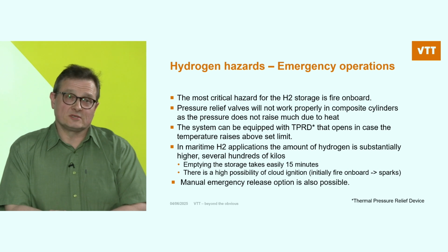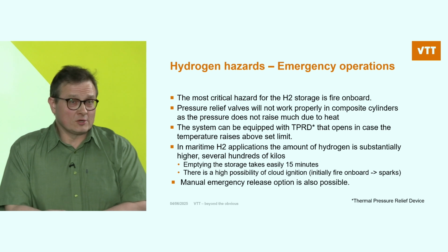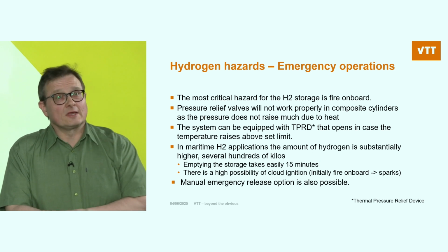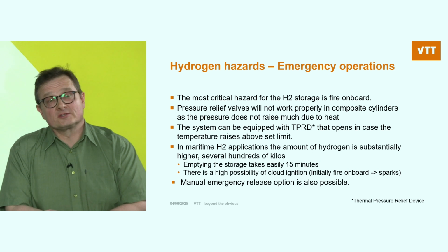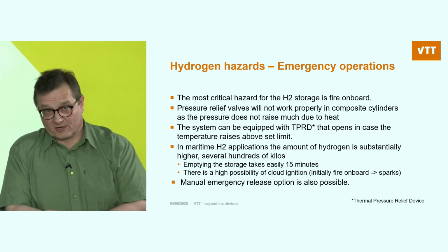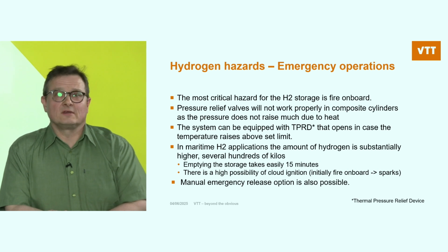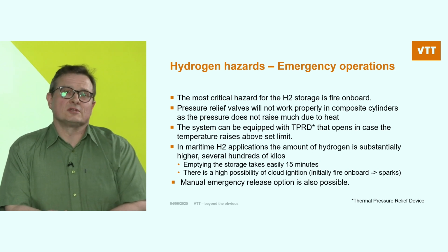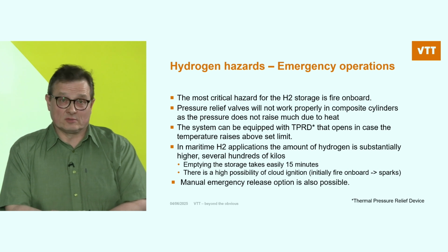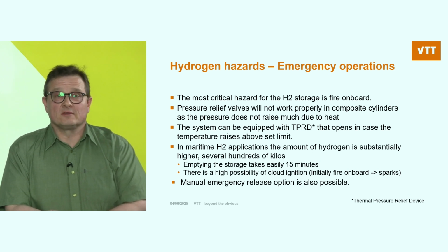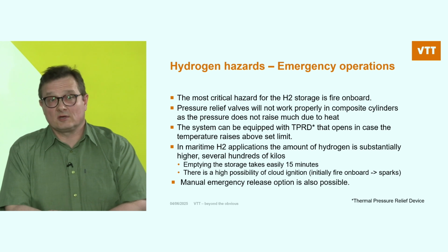One problem is that pressure relief valves in the system will not necessarily work properly in composite cylinders, because the composite material is kind of an insulator. The pressure does not rise inside the cylinder that much, and therefore there are TPRDs, thermal pressure relief devices, in the system that open automatically in case the temperature rises above a set limit.